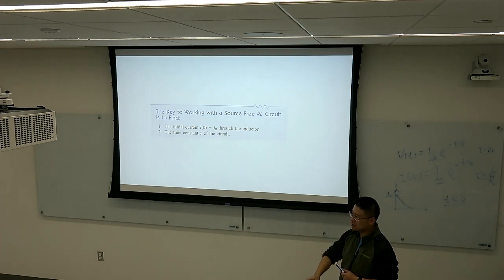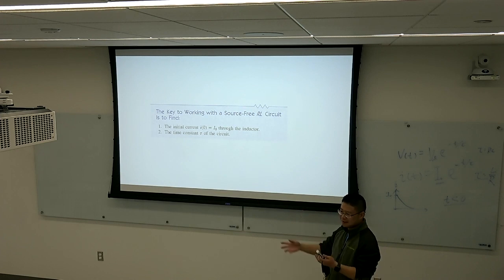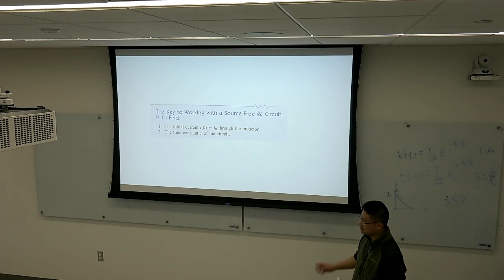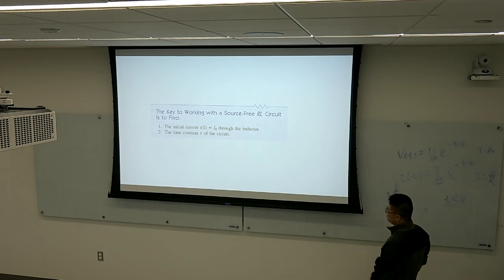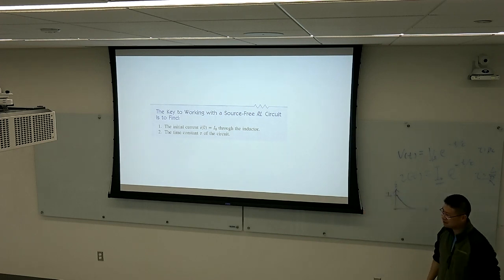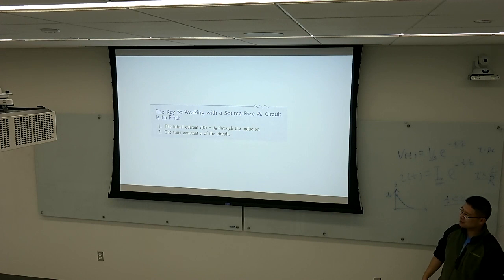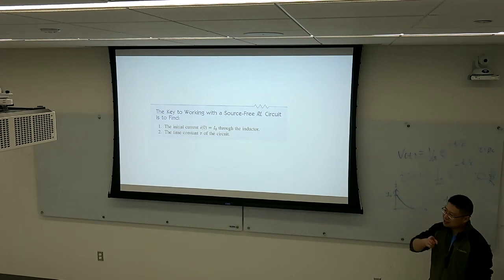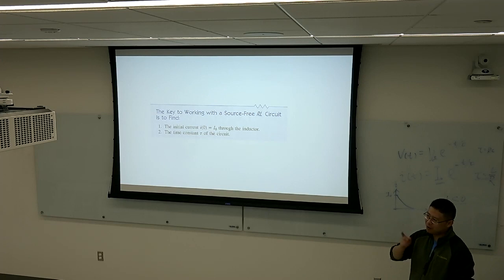capacitor as open circuit, and use KCL, KVL, loop analysis or mesh analysis to calculate the initial voltage of the capacitor or the initial current of the inductor. Later we will use an example.